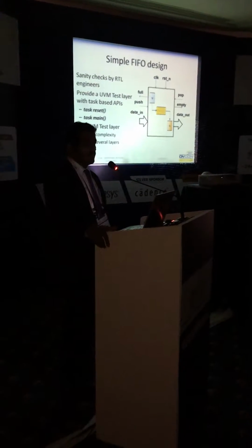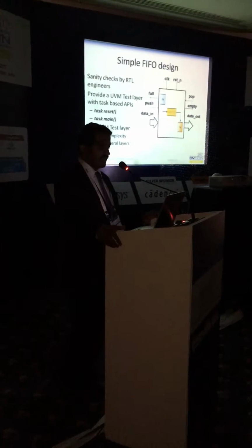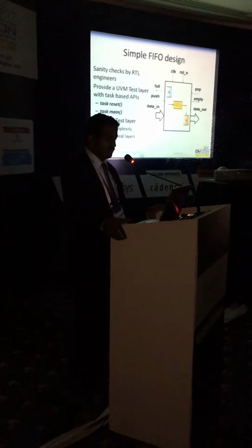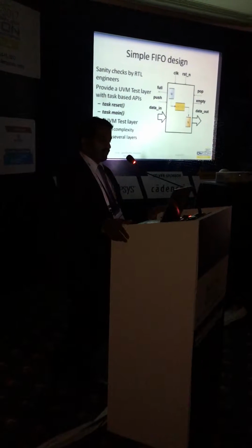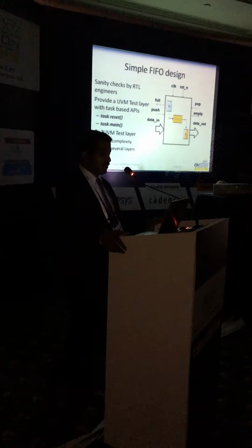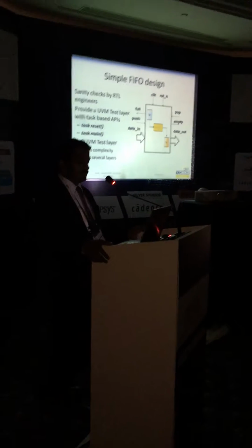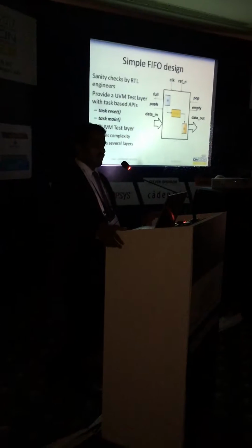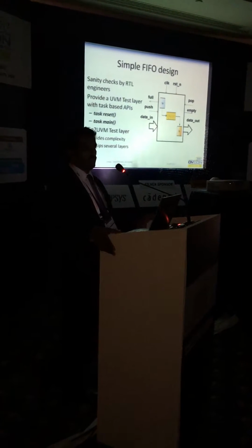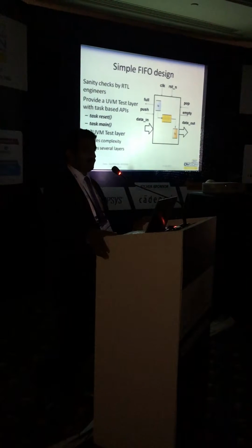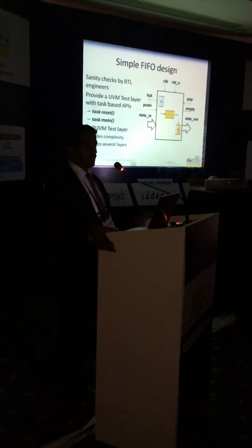So just for the moment, let's take a very simplistic case of a FIFO. Some of you perhaps have seen this slide deck in the FPGA talk. Sorry, we have reused this slide deck. But essentially, if you're an RTL designer having a FIFO like this, with a couple of signals, and you want to write a sanity test, what we provide in GoToUVM is two tasks. We ask you to fill in the reset and main. In fact, to be precise, it's only the main. You fill in the main, we get things done. You don't fill in the main, we give you a compile error. That's as simple as this.